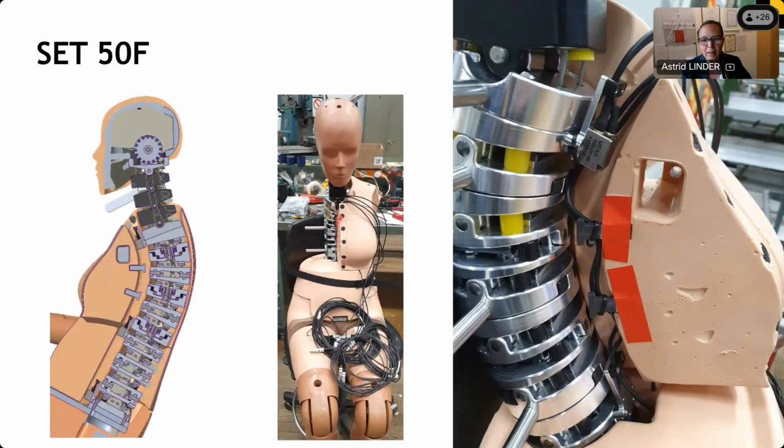So if you were to pick one dummy for sled testing to evaluate frontal whiplash, you would pick the SET in front of the BioRID. Is that correctly understood? Yeah, I would probably. I use the SET both in rear impact and in frontal, but if you want to stay with the BioRID, you can complement it with the average female SET in rear impact, but in frontal, absolutely. This is designed with that impact direction in mind. And that's not the case for the BioRID.